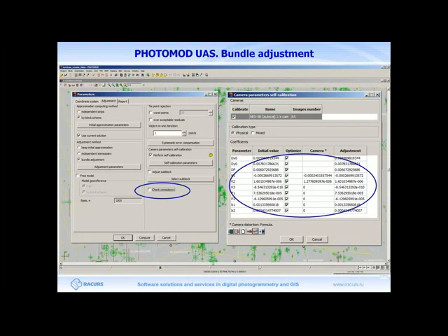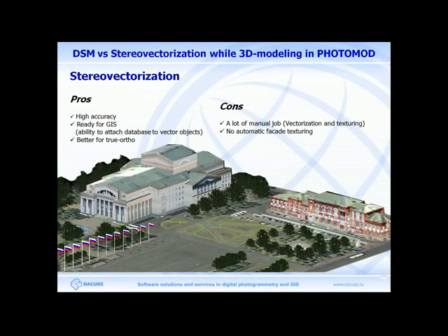At this stage, there is an option, consistency check for images, block adjustment, and central projection. After its activation, the system will check all the basic data needed for adjustment. It means stereo pairs, triplets, and enough ground control points. If the data is insufficient, the program gives an error message and the adjustment will not start. The camera self-calibration process has been optimized at the same stage of block adjustment, on the right screen.